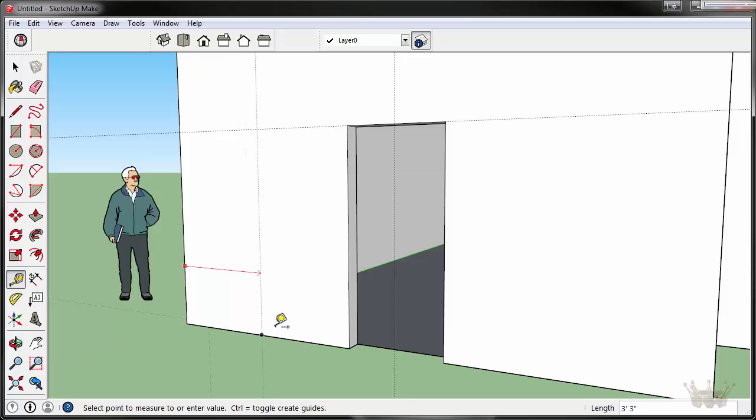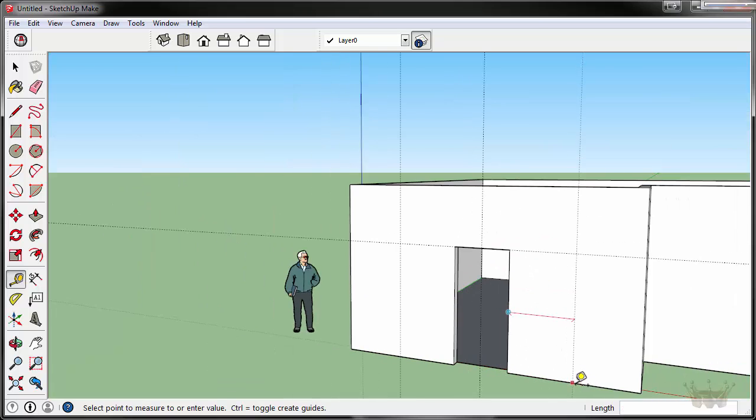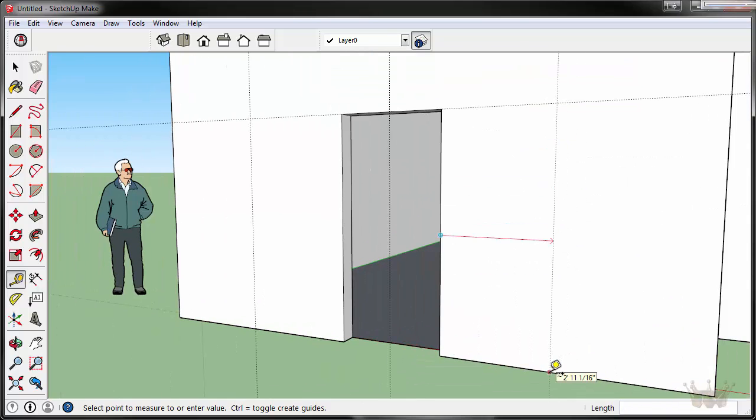If you do not find the midpoint initially, escape off the tool and try from the other edge until you get the cyan dot at the bottom marking the midpoint. I'll do the same thing over here. There you can see I don't have the dot just yet. So I'll escape out and try it from a different side until I get it.